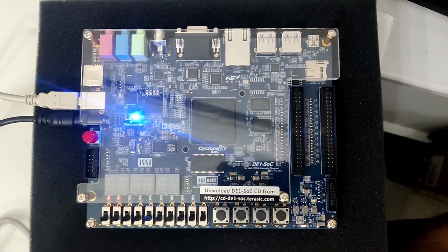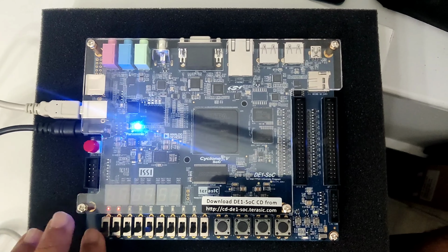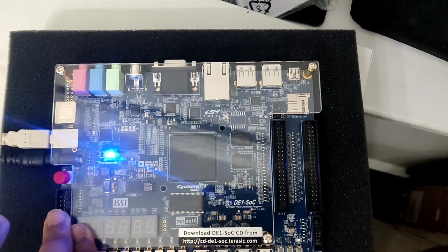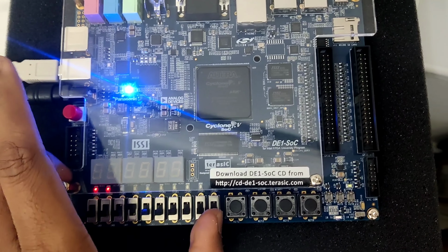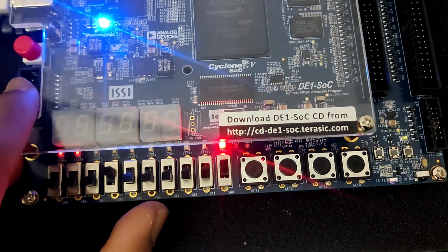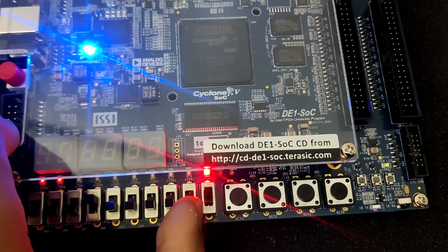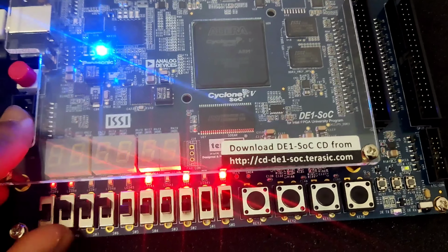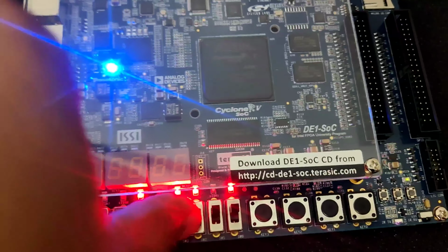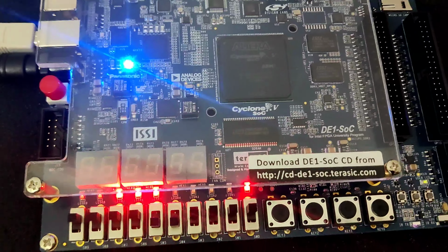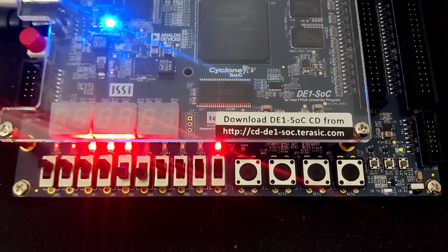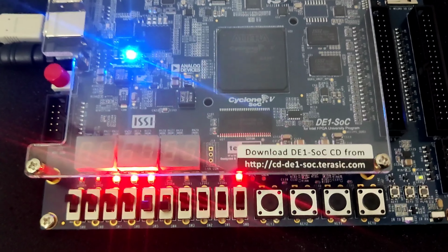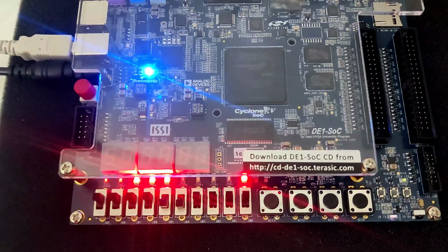Now we can see when all the dip switches are low, we don't get anything, as 0 cross 0 is 0 and 0 cross 1 is also 0, and when we change the inputs to 1 cross 1, we get the output as 1. And when we do 1 cross 3, we get 3, 3 cross 3, 9. Similarly, we are getting the maximum output as 225. So this concludes the first part of our homework 3. Now let us design the same thing by using the 7 segment display.